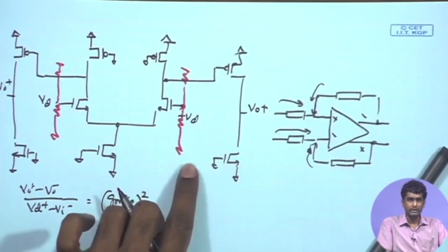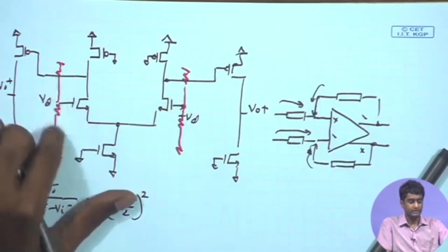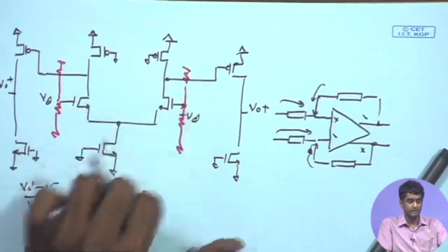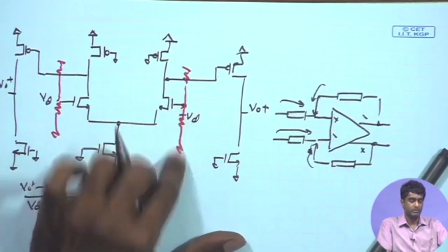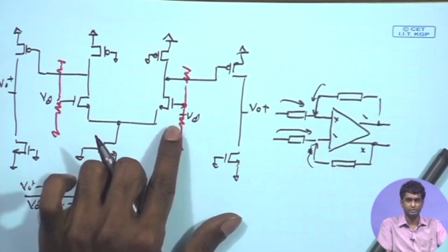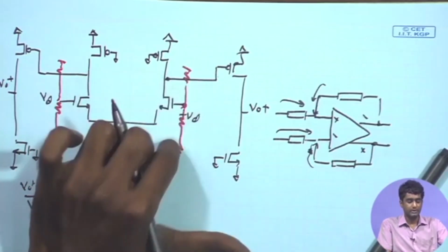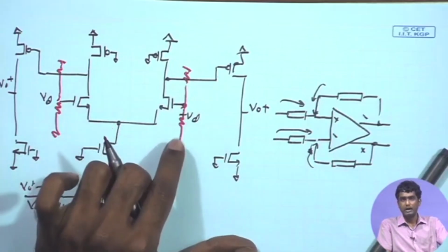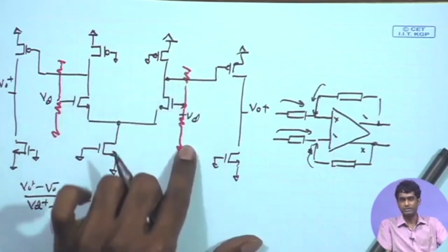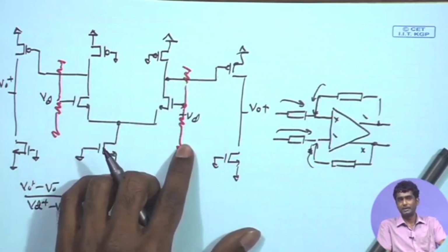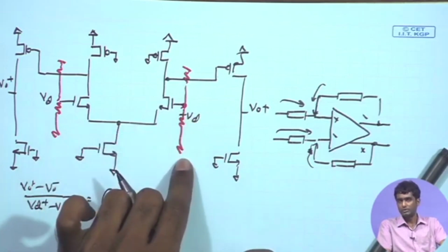Likewise, it will also degrade the input impedance. So here putting the resistive dividers will degrade the input impedance. Rather than the signal coming at the gate through the capacitors, you are now having a low pass filter formed with the help of this resistor. So it is going to affect your frequency response, input impedance and noise, and therefore using these resistive dividers may not be a very good option. Apart from that, this will also waste some of the static power, because if you are having a voltage divider, unless you are having very large resistances of mega ohms range, it may burn a few microamperes of power, and that can also lead to wastage.